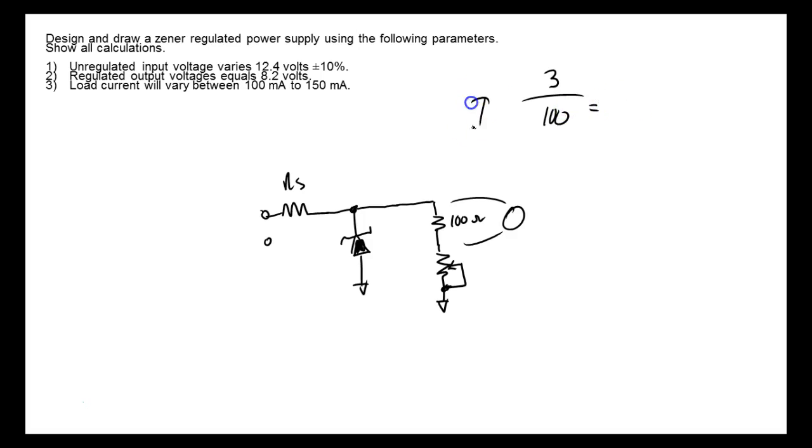So I is equal to V over R, right? So what would that be? What's that? Okay, so right now you know that every volt is going to be 10 milliamps. So you don't have to do calculations anymore, right?